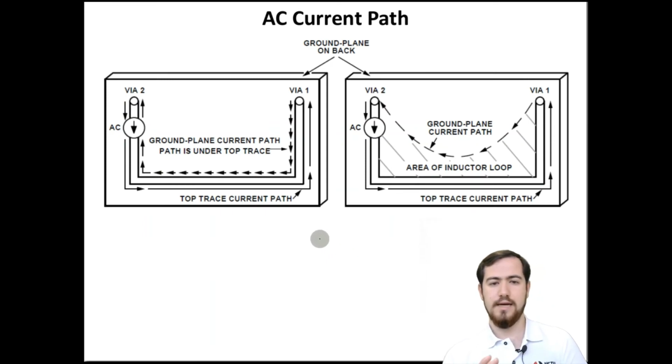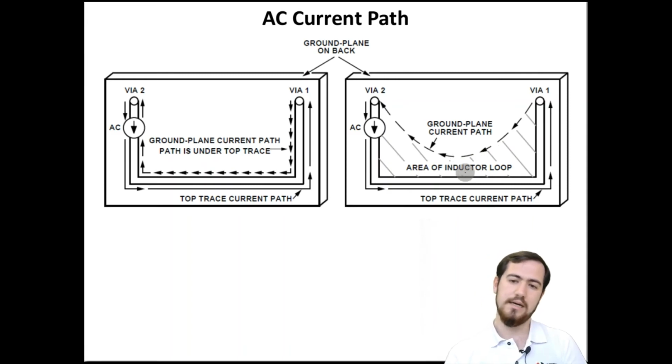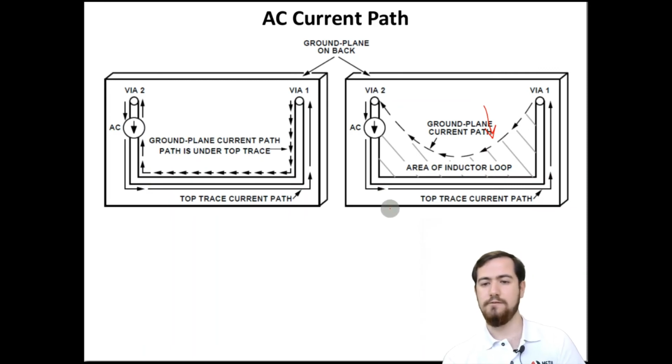Okay, the actual answer for this with an AC current should be like that, because we know that the copper also has some resistance, so it optimizes the inductance and the resistance, and it follows a path which is drawn on the bottom side with these arrows. So that is the most optimum path for a current to flow if we consider the resistance and the inductance as well.